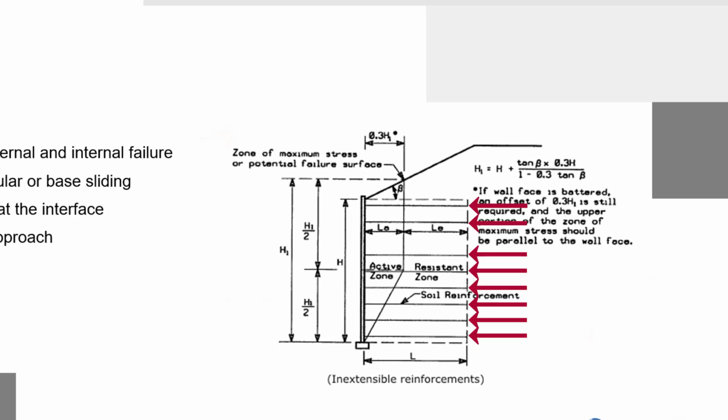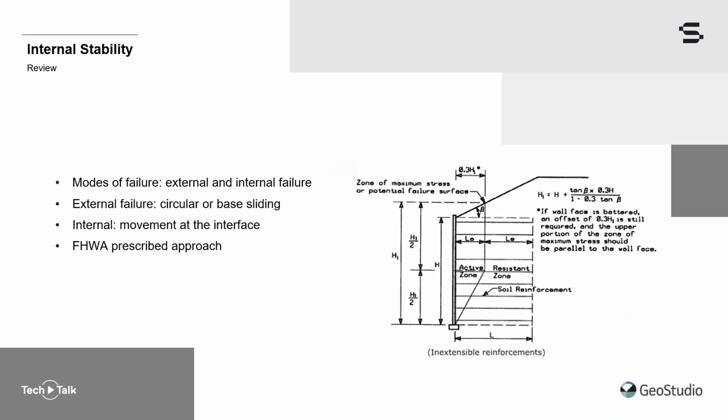The load resistance at each of the reinforcement layers is compared using a semi-empirical analytical solution. The tensile load induced in each layer is calculated using a slightly modified version of the Rankine earth pressure theory. The pull-out shear resistance is determined essentially using an interface coefficient of friction and the vertical effective overburden stress.